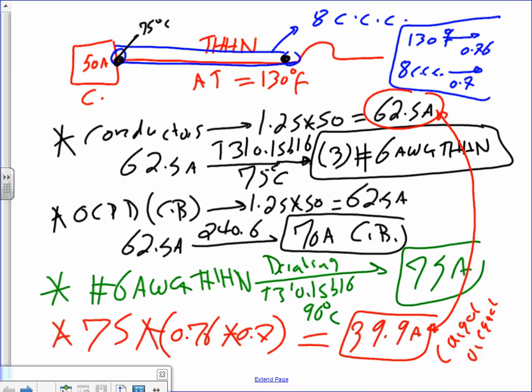Larger or equal. Huh? Just paralleling them to get to 68? You can't parallel more than 1/0. 1/0 is the minimum you can parallel. Everybody understand? No parallel. You can't parallel a conductor less than 1/0. That's the rule. Except there's an exception, of course, for every rule.